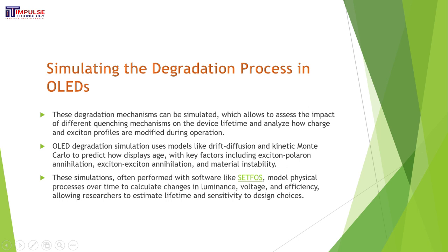These are the separate tabs given in SetFos: quenching, photon quenching, and lifetime. You can use these tabs to simulate this type of process. OLED degradation simulations use models like drift diffusion and kinetic Monte Carlo to predict how displays age. So these are the separate modules and these are the separate tabs.